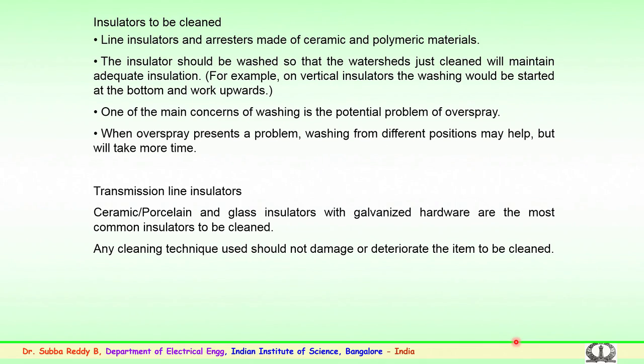Transmission line or distribution insulators of ceramic, porcelain, glass, which are connected with galvanized hardware, are the most common insulators which are to be cleaned regularly. For any cleaning technique employed, the main intention should be not to damage or deteriorate the surface of the insulation system during the cleaning process. This has to be kept in mind by the utility personnel who do the cleaning.